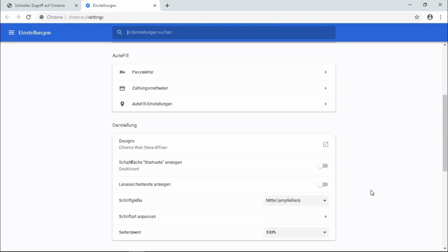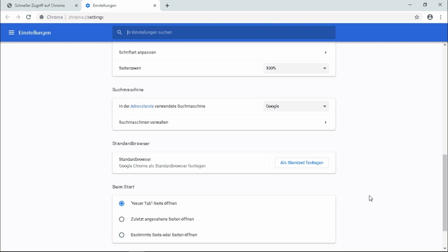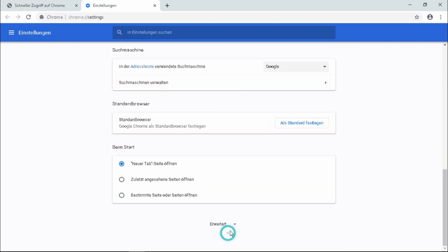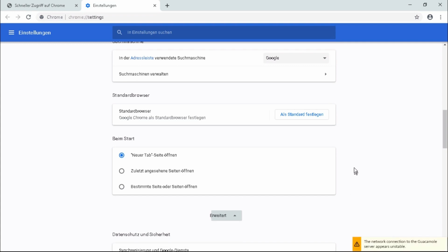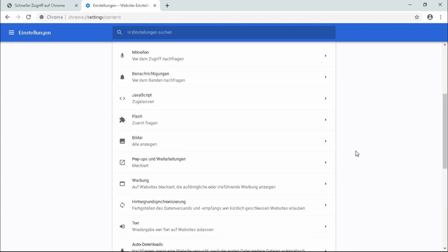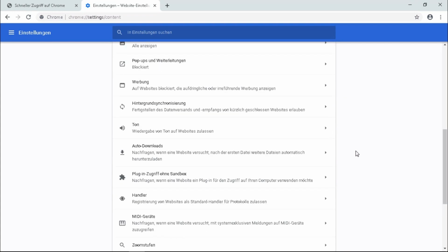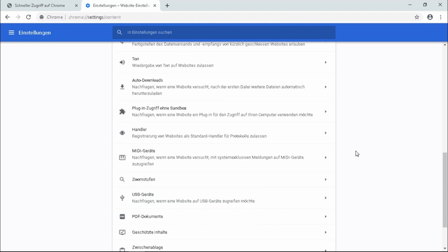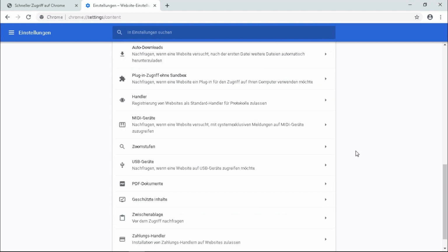So we do the same thing as yesterday, what I did in WinCC 7.5. We define our structure elements here. So we know we have a tank UDT, which consists of the elements content and color. And now we just link the elements in the screen, which is then for color dot color.